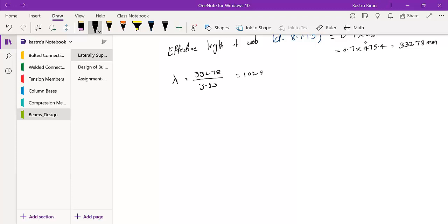So you know the I section belongs to a buckling class. If you want, you can solve it, or you can directly take the value of FCD from Table 9C. It's up to you. If you want, you can cross verify with the answer which I am solving.